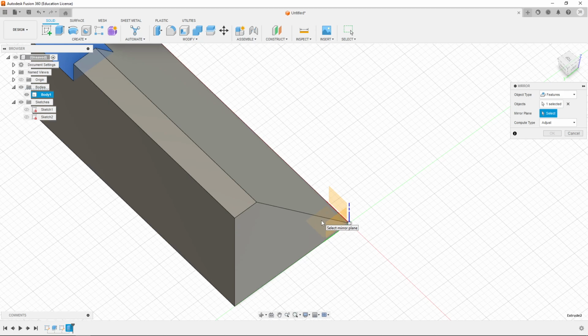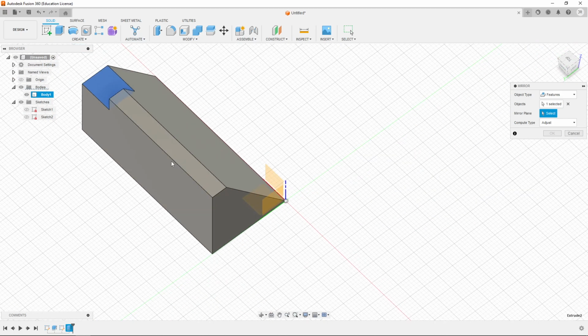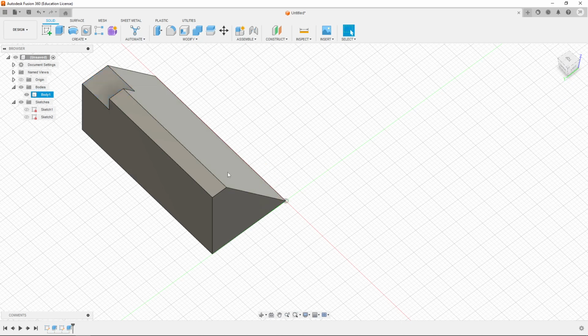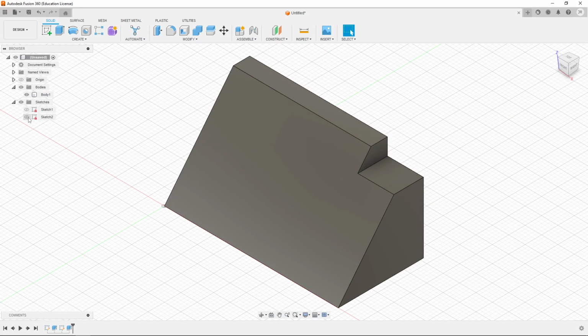So I think we're going to stop this and we're going to kind of unwind and say, you know what, instead of doing mirror from the 3D perspective, let's go back to our sketch and pull that instead. Or recreate that or mirror that instead, and then we'll be able to cut out that second half. So I'm going to cancel. Unfortunately, even though we could do it, and we could definitely make a plane right in the middle, for now we're not going to do that. Let's go back to our sketching. That might be the better choice for us as beginners. I'm going to cancel. I'm not going to worry about this. So I'm going to remake my sketch to appear. So again, I have more options.